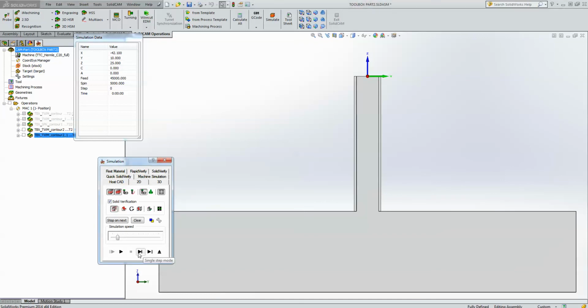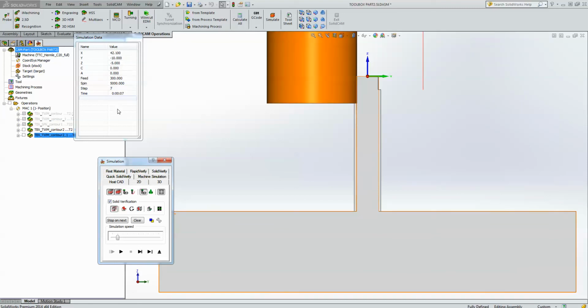Now what's going to happen is as follows. The first step that it goes down to is going to be 2.5 millimeters. Not 5 millimeters, but half of that. It goes across, machines that, fine. Now when it goes to the other side, now it's going down to its full 5 millimeters. Now note, when it goes down to this full 5 millimeters, it still has 2.5 millimeters of support over here. So you still have support on the other side of that wall. So you're not completely on thin grounds over there.